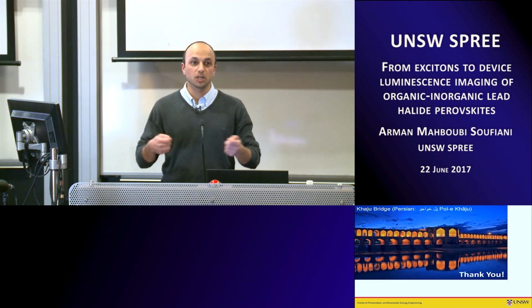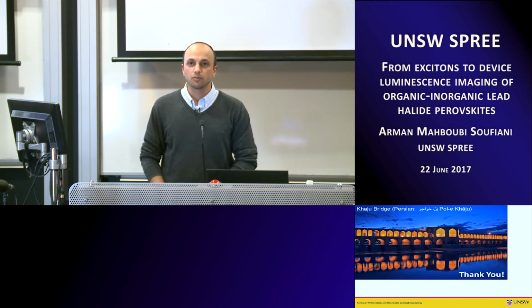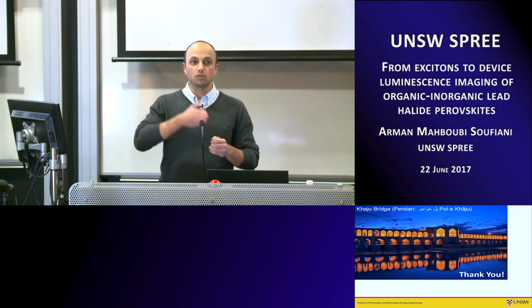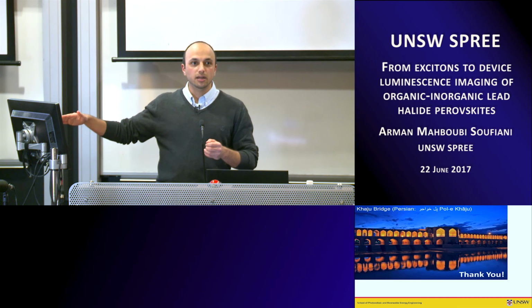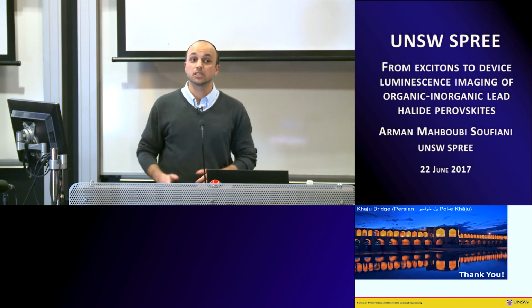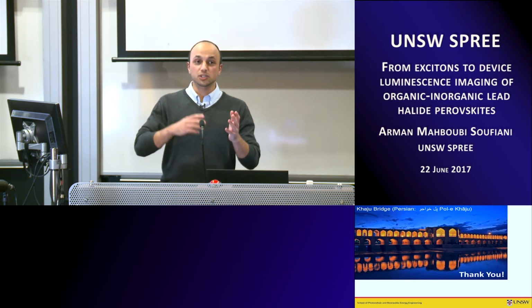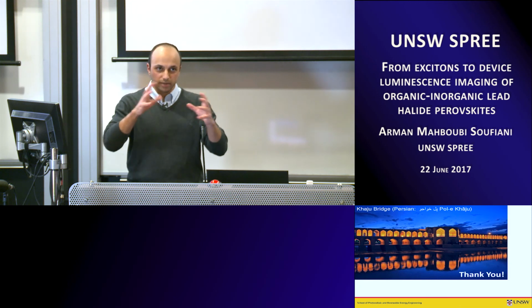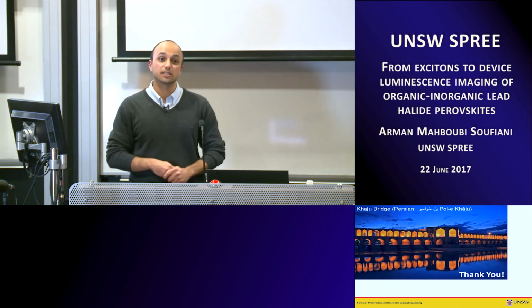So when you bias the device, for instance, let's say we want to do EL imaging and extract the series resistance image. While you bias the device, the EL intensity starts to rise, saturates, and then degrades, even in very high efficiency cells. So this is an issue because you need 2 different biases, and then manipulate the images and extract the series resistance, right?